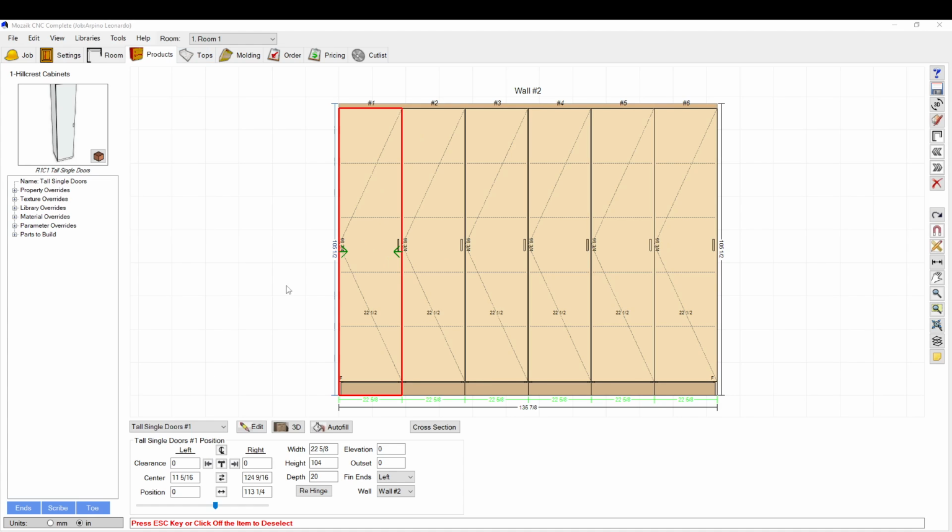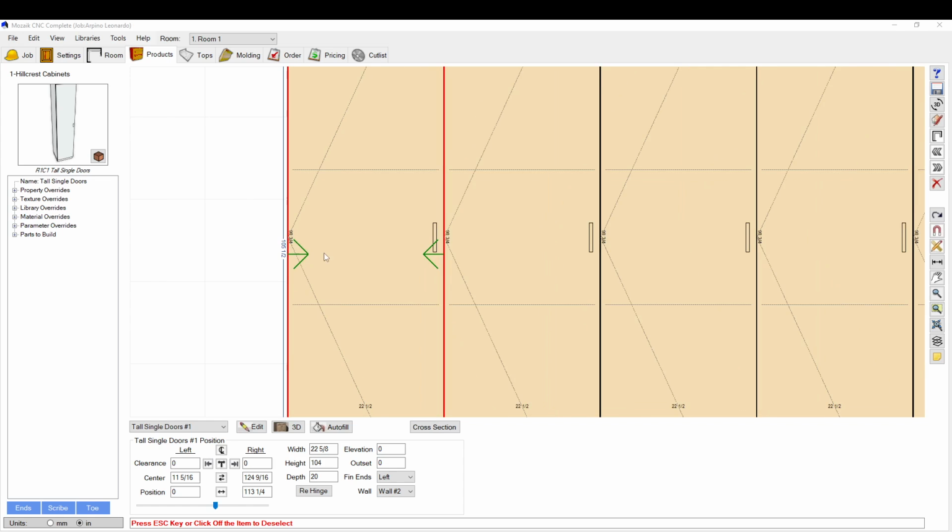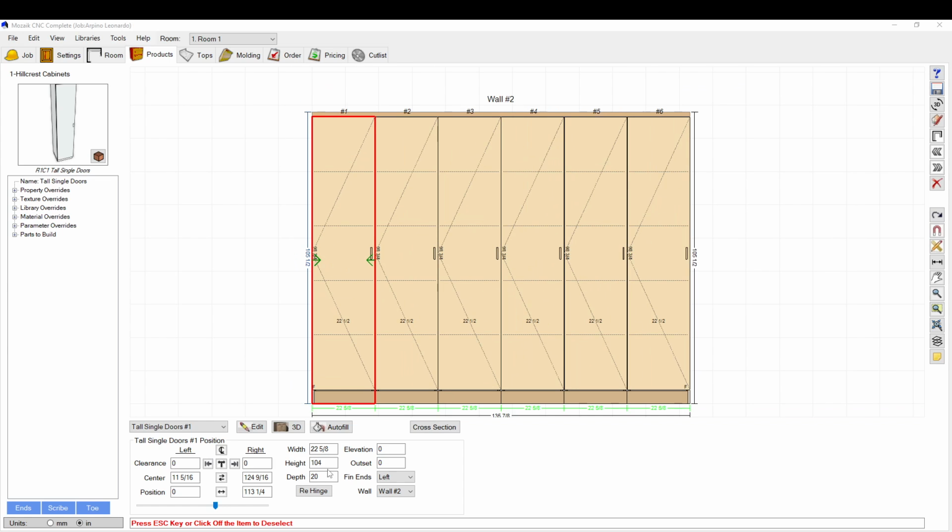You're going to want to set it depending on the size of your CNC machine. The one that we have is a 4x8. So as you can see, these parts are 98 inches long. So you want to make sure that it's going to fit on the machine, and/or split the cabinet in a way that it'll be able to fit on the machine. So for this case, I'm going to make this 101 perhaps, we'll do it.